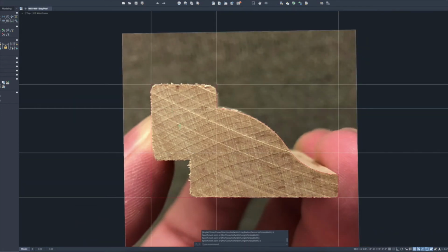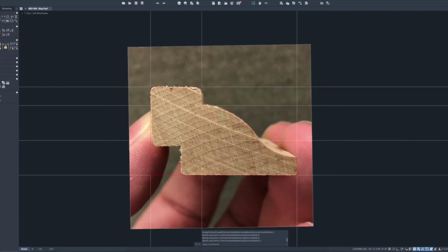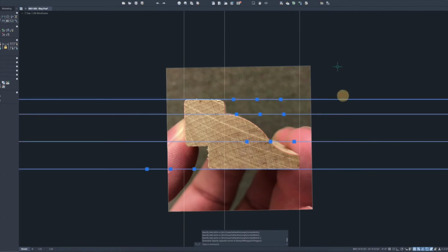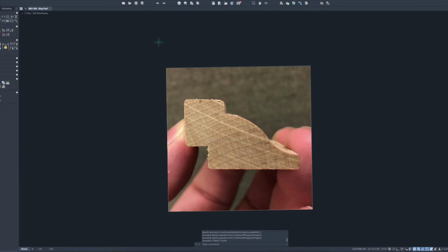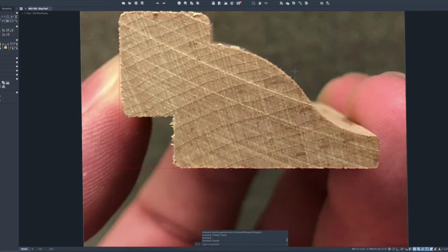Things can get much more elaborate, but this is what I had laying around, so we're using this just for simplicity's sake. So now we can go through and get rid of all of the excess lines, and we have a closed polyline here. Now, I could do this section with this line, and then just trim off all my construction lines.